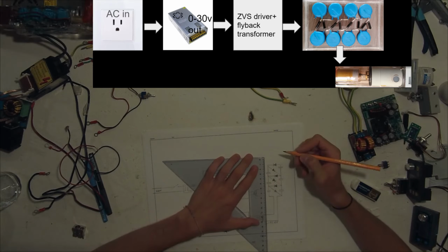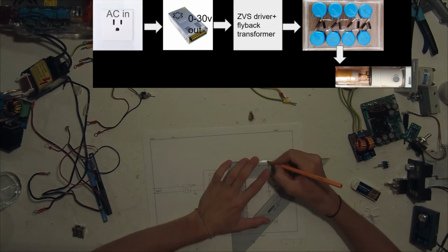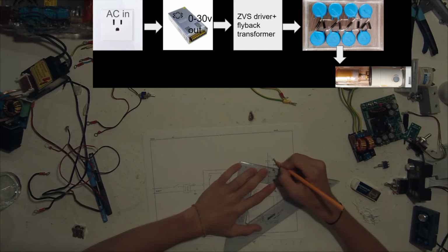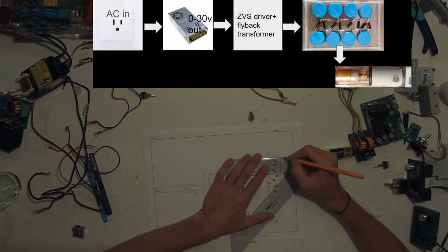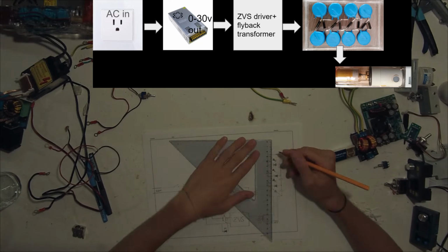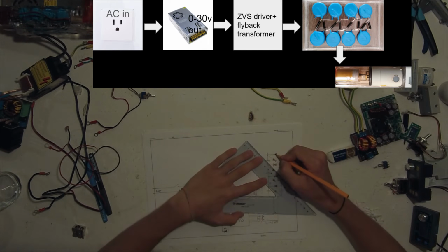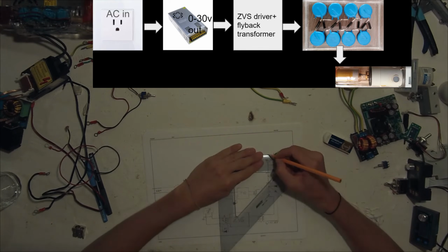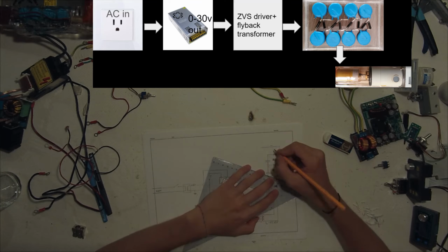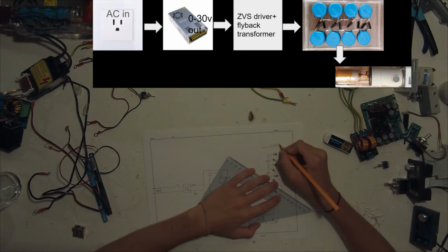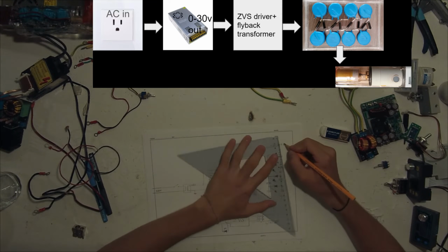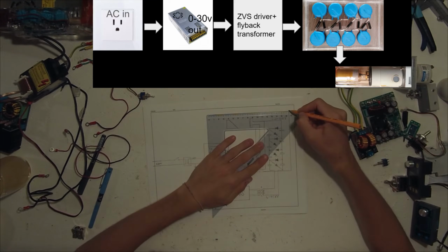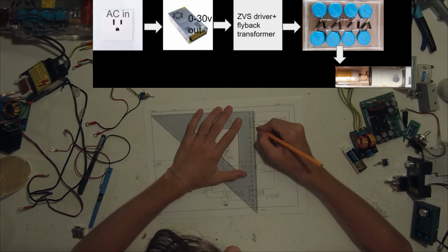It has a negative polarity configuration that is shown in the drawing. To have a positive polarity you just need to invert the direction of the diodes. In my case I need the negative because, as I said earlier, the structural analysis X-ray tube needs a lower potential with respect to ground to accelerate the electrons from the filament to the anode.